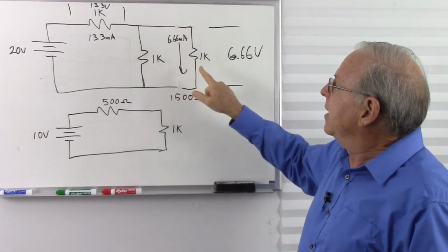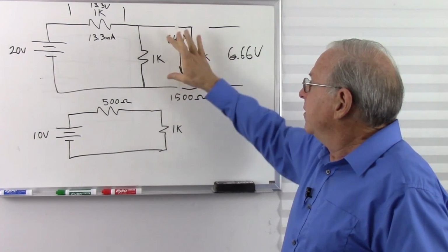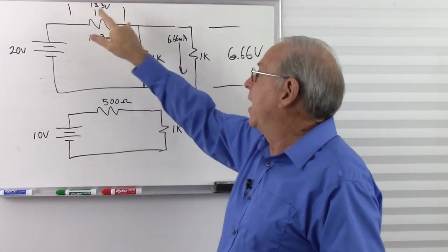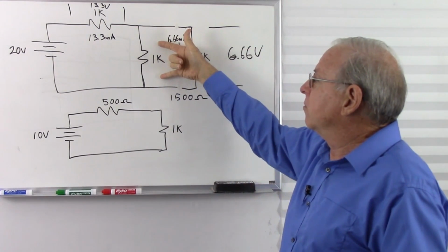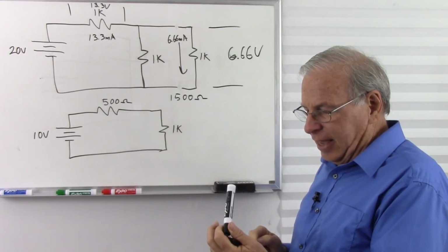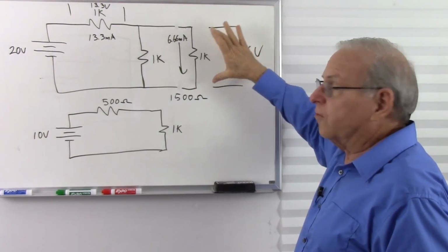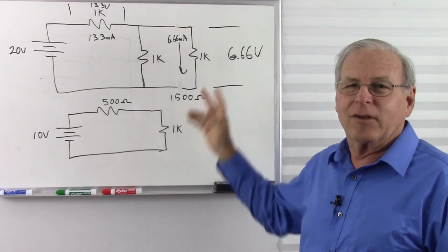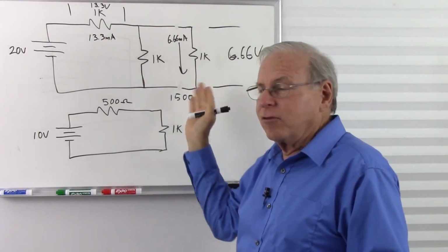resistor. By the way, I did this by Ohm's law, but we could have also done it as a voltage divider. Here we have 500 ohms and 1,000 ohms, so we have 2 times the resistance we have here. So 2/3 of our voltage would be here and 1/3 of our voltage could be there. We could just take our 20 volts and divide it by 3, and that gives us 6.66 volts, and we do that division, and that gives us the voltage across the lower resistance. This is 500 ohms. We'd have 6.66 volts.